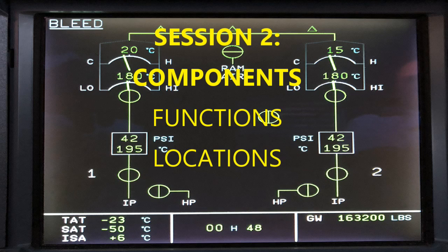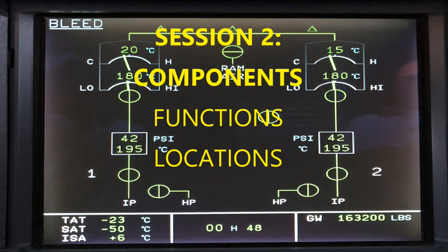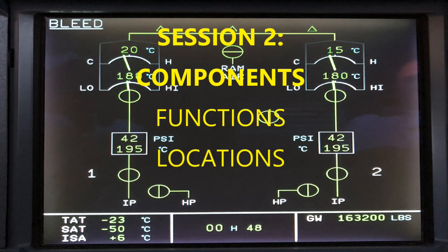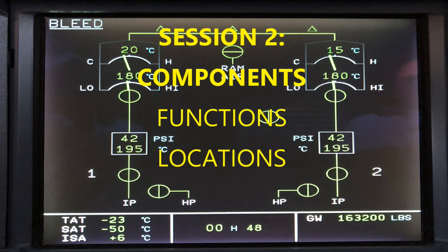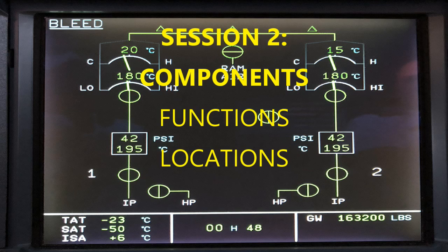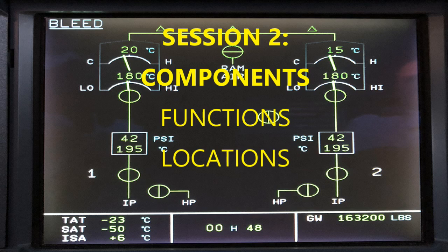The start sequence is kind of the beginning of what happens here involving the load valve. You've got the start sequence that happens with the APU. Of course, this is standard, because if you read or know about the other ones, the APU needs that 95% speed. Obviously when it reaches that and goes beyond, then we're good to go. You've got the APU actually doing some work. And that's the load valve, like I explained, as far as what it does.